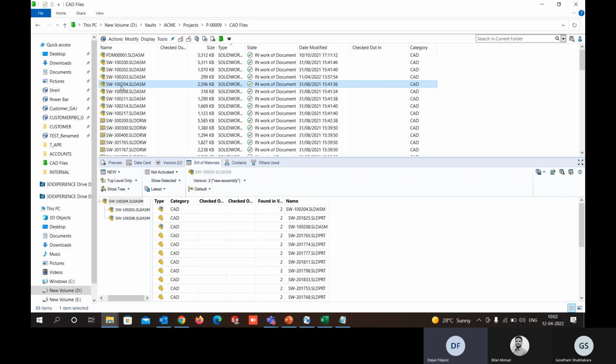Just make an assumption that you can run two trials, the first trial being that we make a 3D file of a sheet metal piece. We make a corresponding DXF file for the unfolded shape. Then we want to move the DXF onto a location that will be used as the cutting file for the machine.